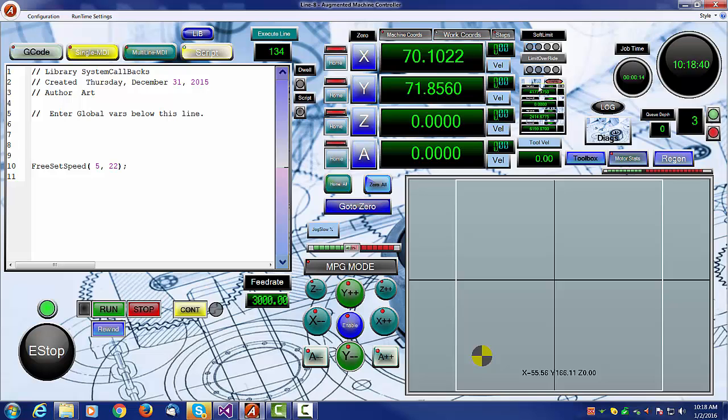So these 4 axes work totally independently of running programs, and because of that I call the Cartesian ones orientation axes, and the ones that you set as speed are conveyor belts or spindles or anything else along the line. I can't tell what you're going to use those for, so really they have no name or defined function.